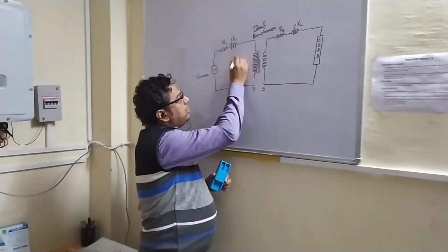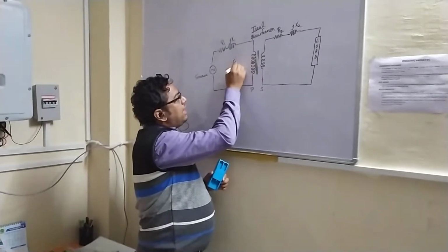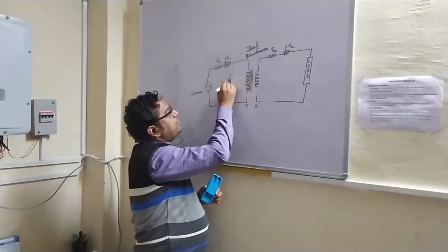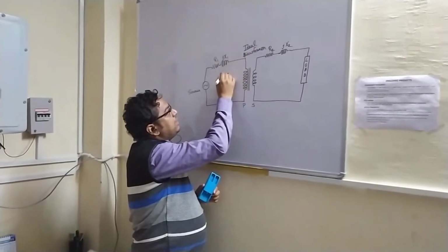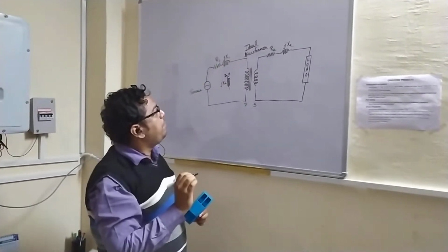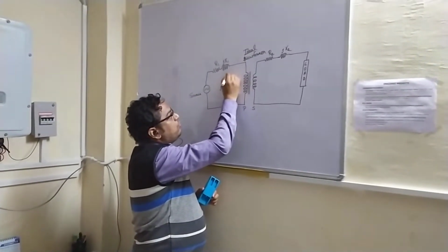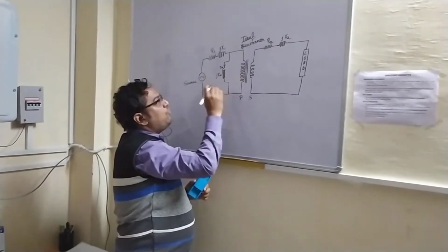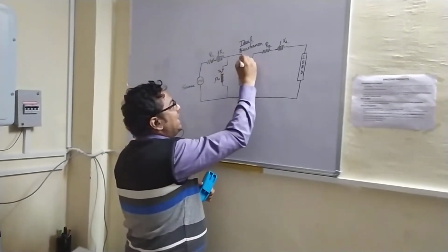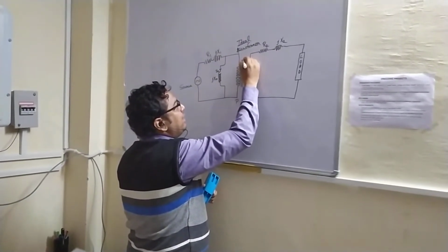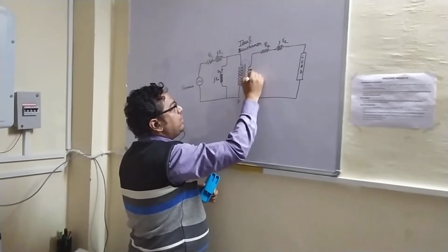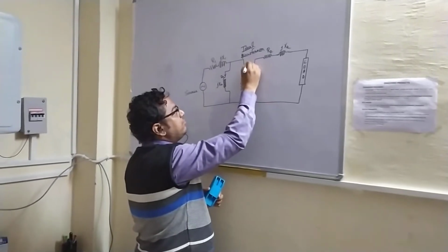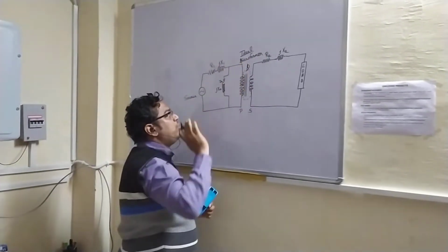So for magnetization, we are considering that there is a coil jXM through which some magnetizing current is going to flow. Now when this current flows through this magnetizing coil, some amount of flux is produced, and then that flux will flow between the primary and the secondary winding. This is going to happen.